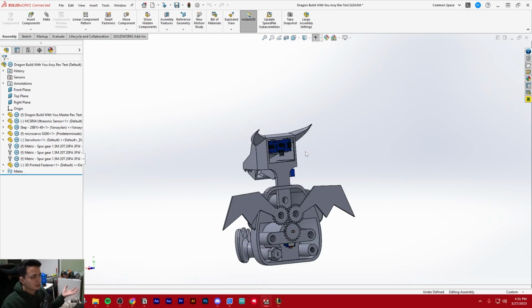All right, so sometimes your parts are going to break, and basically that just means that you move something or delete something, and another part of your design was referencing that part that you got rid of. SOLIDWORKS doesn't know how to reconcile that and update your part accordingly. So there are 2 different types of breaks or failures. It's a red error or a yellow error.